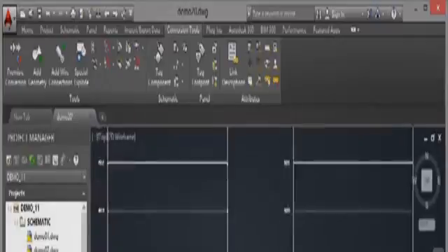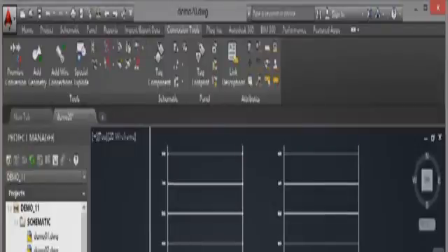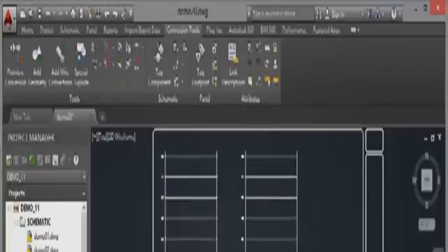So I'll zoom in a bit. And again, you might want to just zoom out slightly and just get this just right on the screen. I'm going to click down here and just drag that crossing selection window up to there like that. Press enter to confirm. And now I can modify those line reference numbers. So you can see there, rung spacing, rung count 2, reference start 809, and so on. So they're all in there. If I OK that now, it's actually updated those for me.